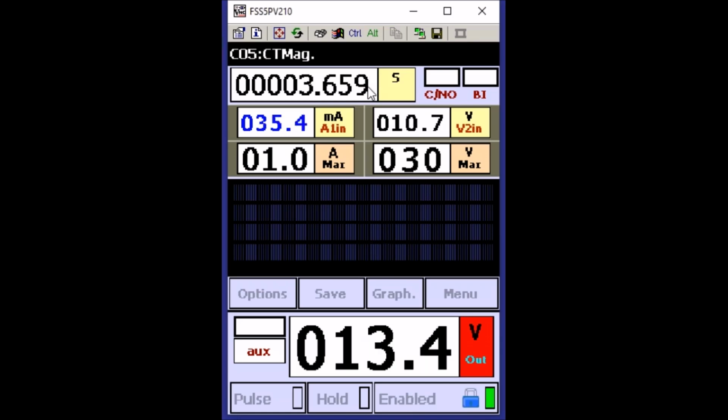So you see, okay, the time is just elapsing, and you can see what's the current in secondary. Okay, this is just a few milliamperes, because the impedance is very high. And this is the voltage ramping. You see the voltage ramping progressively until the maximum is reached.